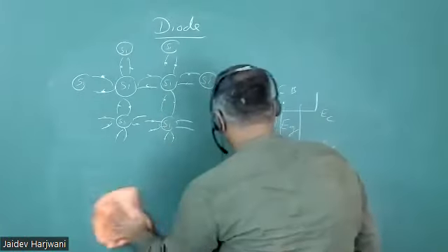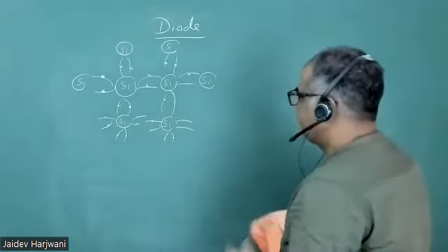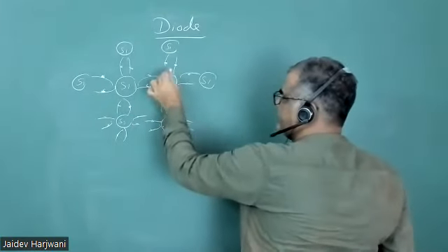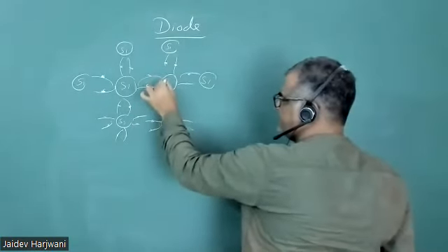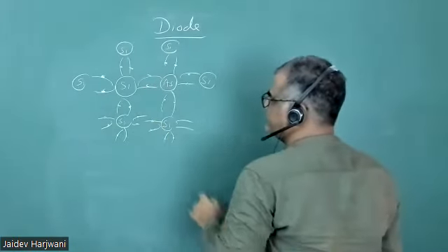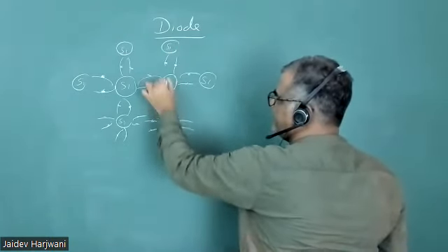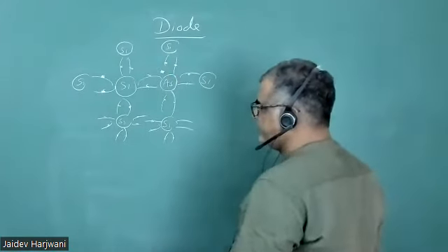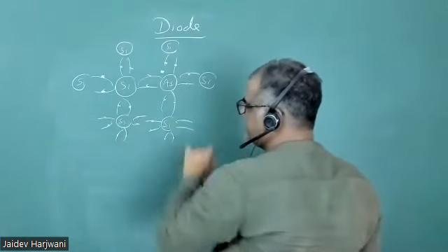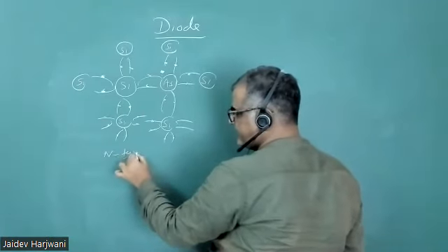Now let us discuss what is p-type and n-type semiconductor. If this silicon in the system is replaced by, say, arsenic, arsenic has 5 valence electrons. Out of 5, it will share 4 electrons with the neighboring atoms, and it has 1 electron left here. Because when you introduce the impurity, suppose this is what I call the n-type material.